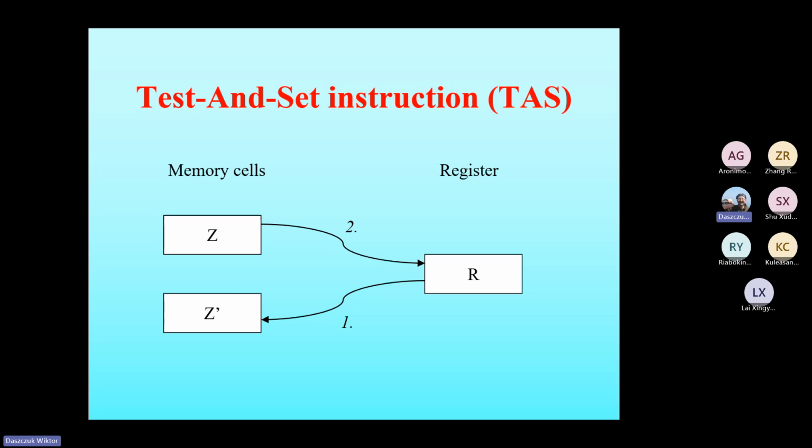If we perform the first access to memory, the arbiter will not allow any other module in our computer to access the bus until we perform the second access. It is a special access to the bus for two consecutive transmissions. So it requires cooperation of a processor with the bus arbiter of the computer.